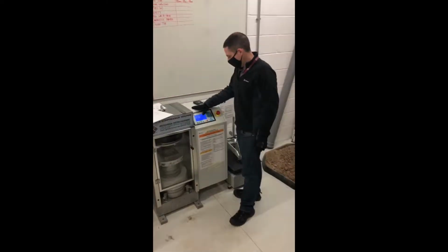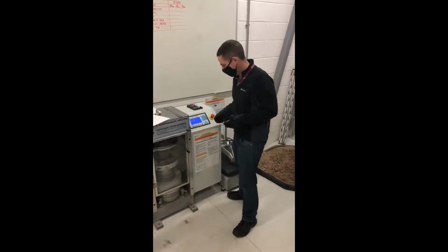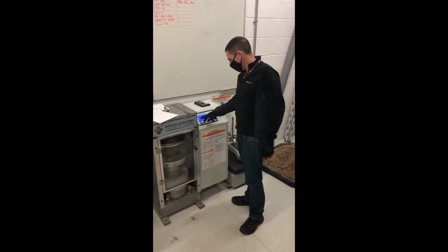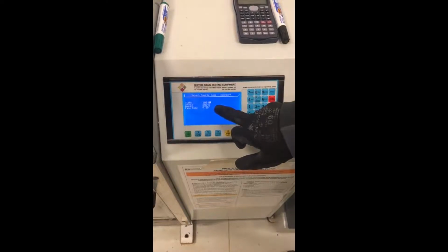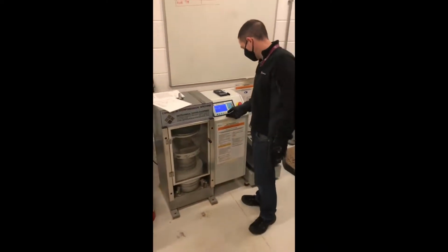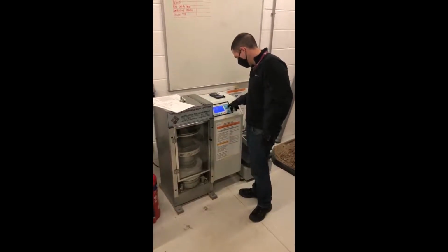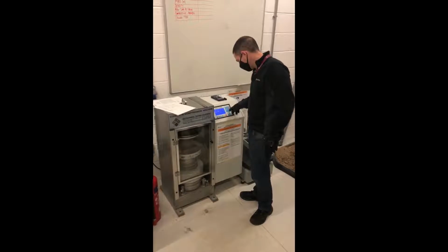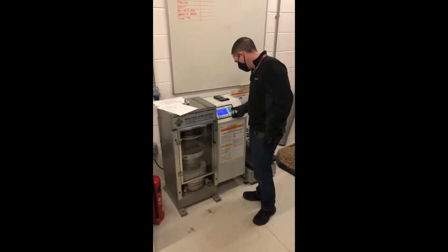And then just use this. This is an automatic testing machine, so it does everything for you. No need to change anything once it's set. What I've done is input on the screen here, you can see I've put in the dimensions to the relevant standard, and also set the pace rate to 6 kilonewtons per second. So that's now good to go. We just escape back through the menus, and then test the cube itself.